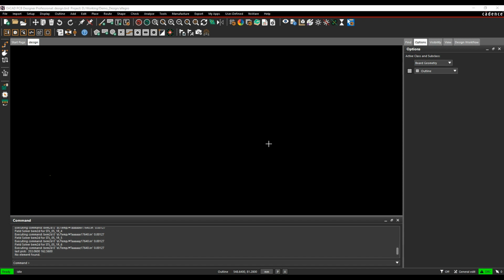Okay, this how-to video is going to talk about how to use the cross-section editor inside the Cadence PCB tools. The cross-section editor or stack-up generator is where you would effectively define the layers of your PCB, the number of layers that you want. You would build this as you would actually build a PCB, so between every conductor material you would have a dielectric piece of material, whether that be FR4 or a pre-preg bit of material, and you can define all that in the cross-section editor.